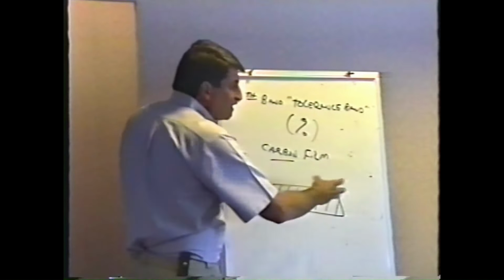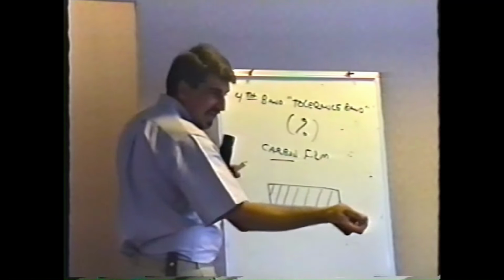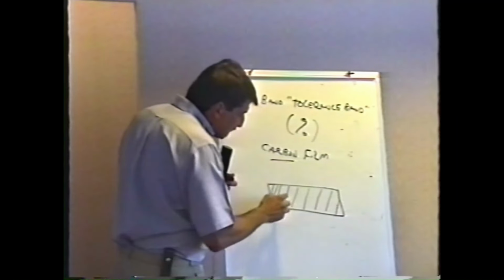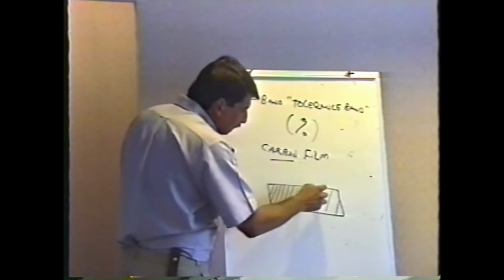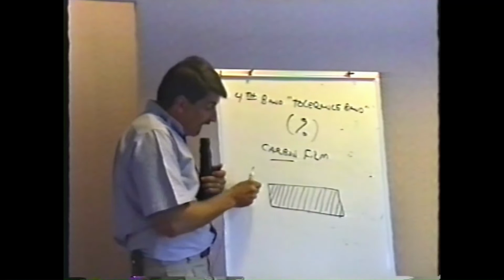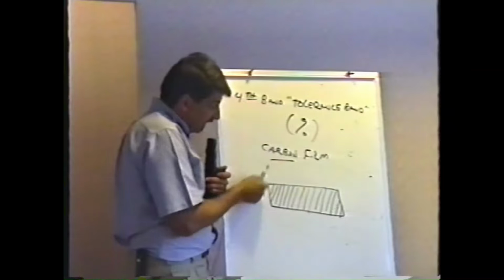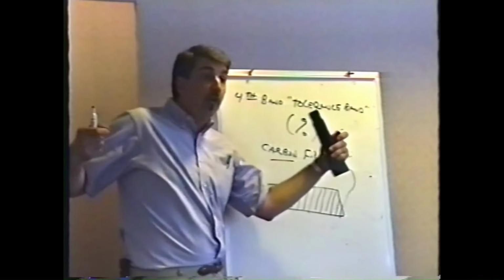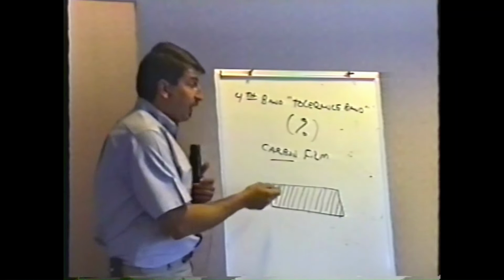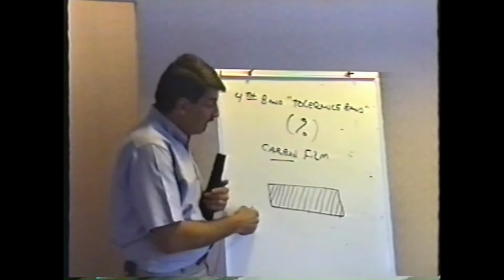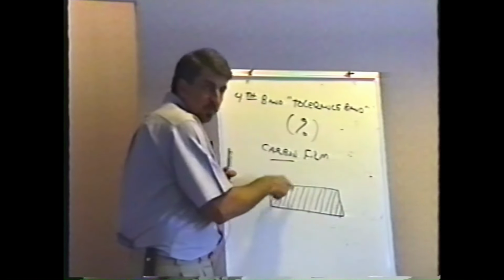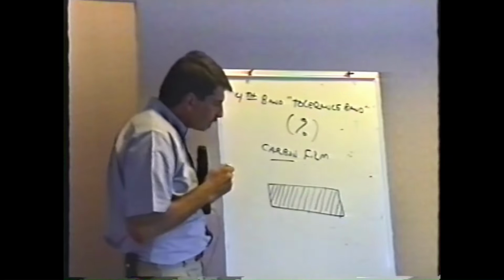The way they change the value of the resistor, the way that same size resistor can be 10 ohms or 10 million ohms, is they make the spiral winding thinner. This makes more resistance because naturally the thinner it is, the more resistance it has. Plus, if I were to unwind it, the longer it would be. They got more spins on it. In fact, on the rare occasion that you see a burned up resistor, if you brush it aside, you can see the burned up part. You can see the spirals wrapped around it.